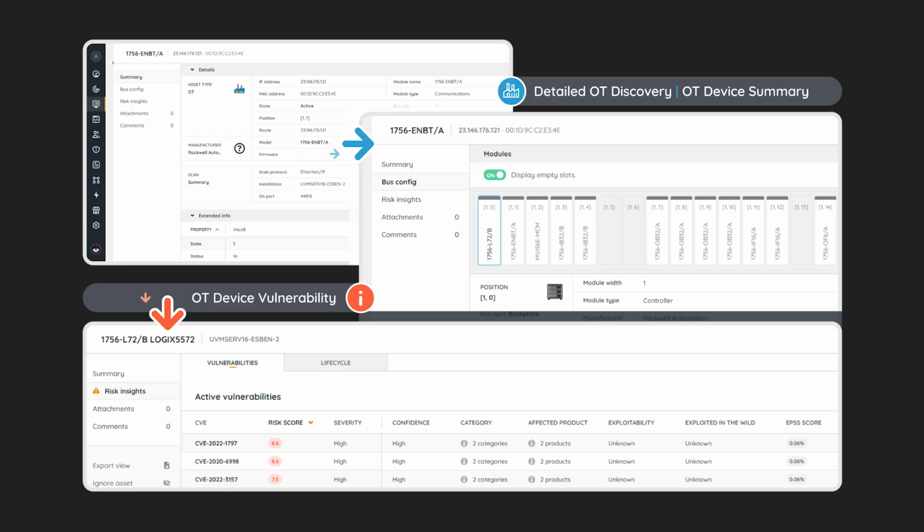First off, we get the information from the OT devices using the ARP protocol. Then we map those devices with the protocols that we have available. And last, we are able to send a request to those devices using the protocols that they support, seeing as we've been able to understand that from the initial information gathering using the ARP protocol. That way, for most of the OT devices, we're able to get all the information without you having to specify which protocol should be used.